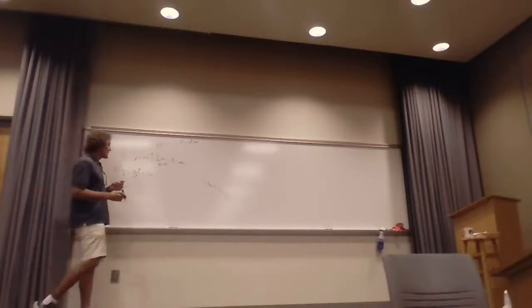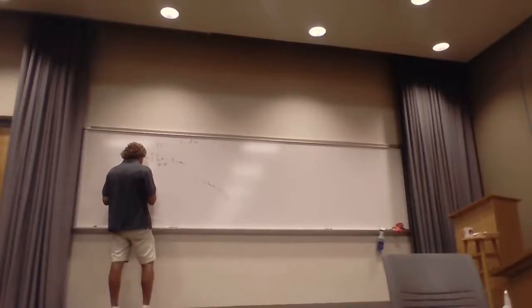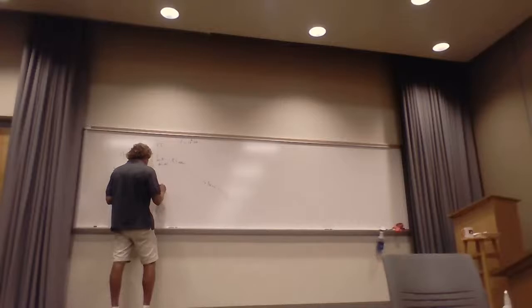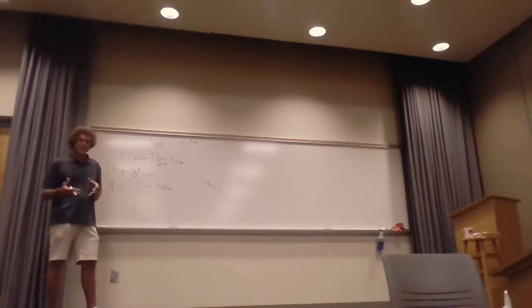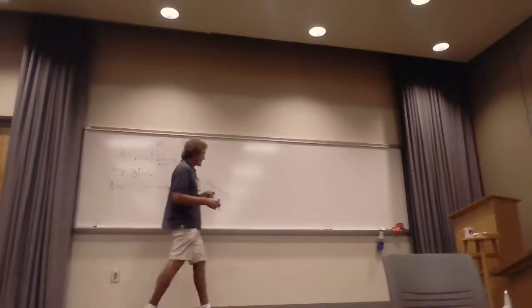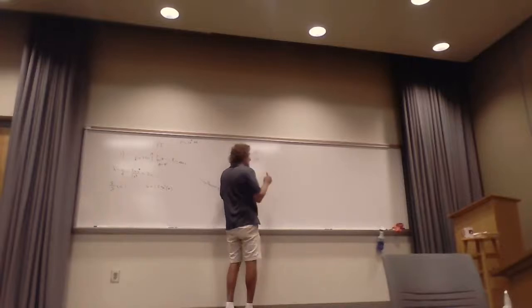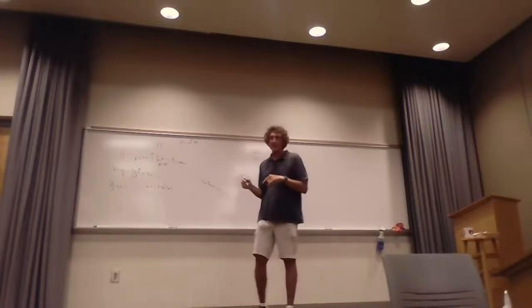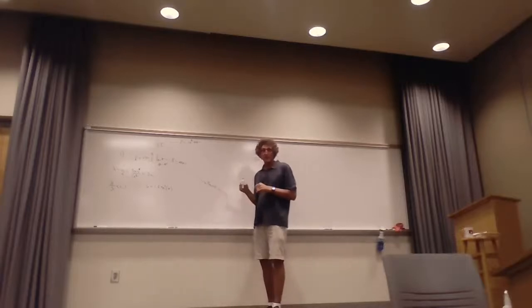Yeah. All right, now if it's a short dipole, the next thing you know is the gain itself will be 1.5 times the sine squared of theta. For all short dipoles or small dipoles, that's understood. Anyway, the first part, I think they asked for both E and H, right, at the point of observation of the field, right? In other words, out here at a range of 4,000 meters, right? Correct, class, everybody? Now, most of you got this right.